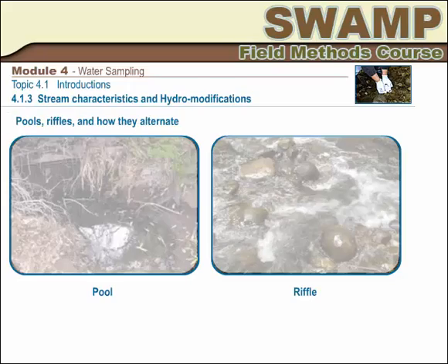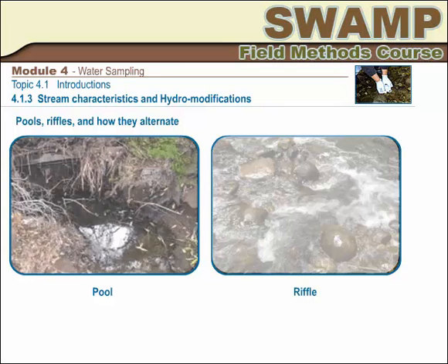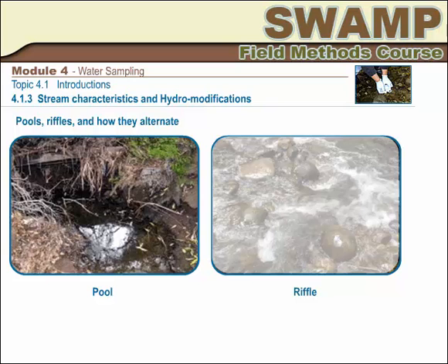In a naturally flowing river, areas of riffles and pools alternate in a predictable sequence and at predictable intervals, which are related to the width of the stream. Riffles are areas where shallow water is rippling over rocks. Pools are deeper and calmer areas. Determining the riffle-pool sequence and stream width can give students an indication of the extent to which a given stream is out of equilibrium with the forces that create it. In most natural streams, the distance between riffles is equal to 5 to 7 times the width of the stream.